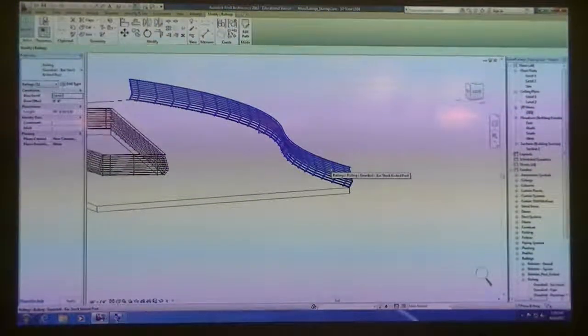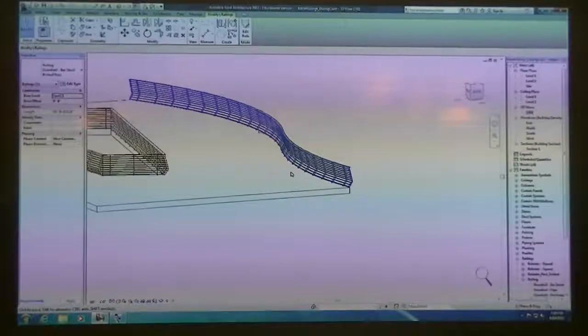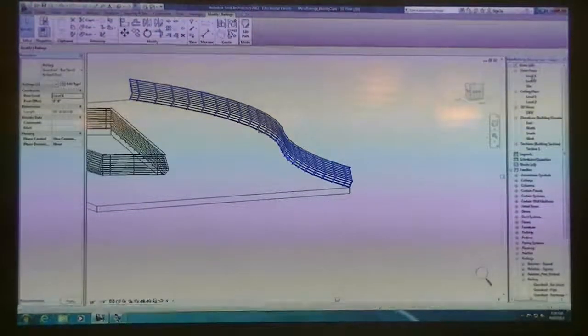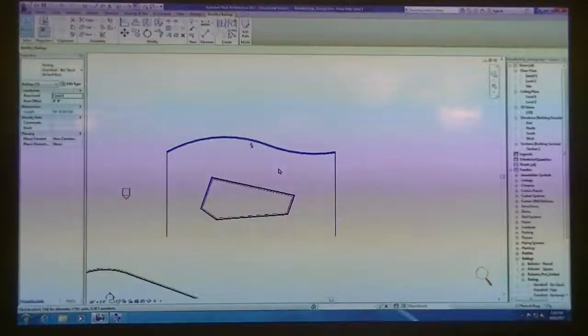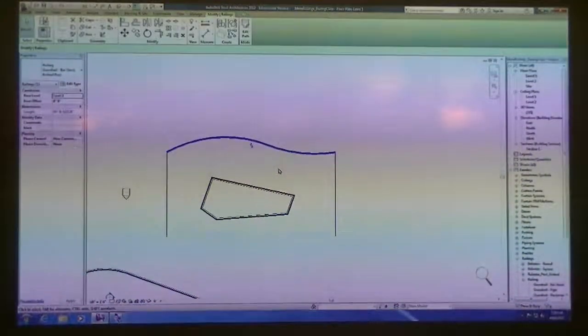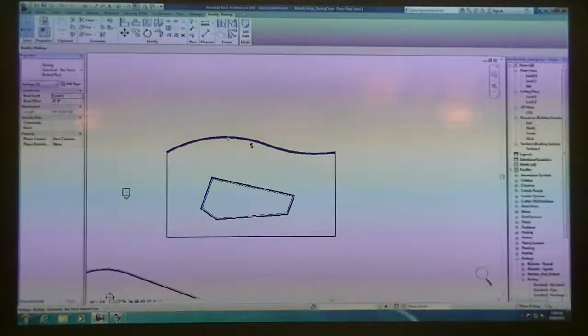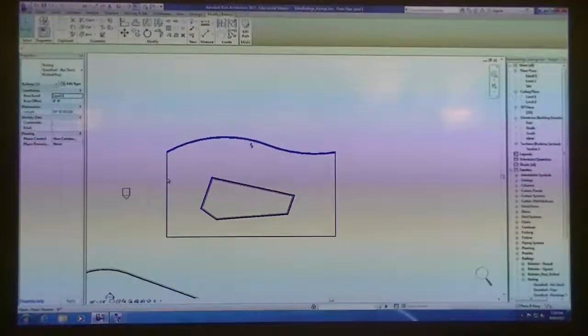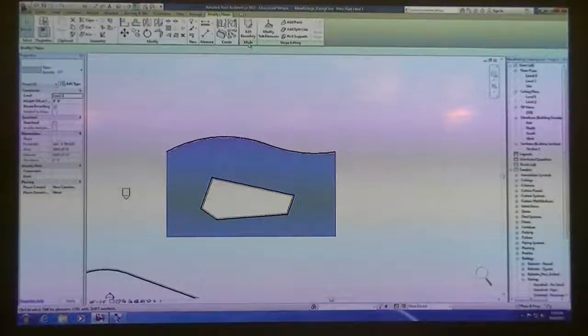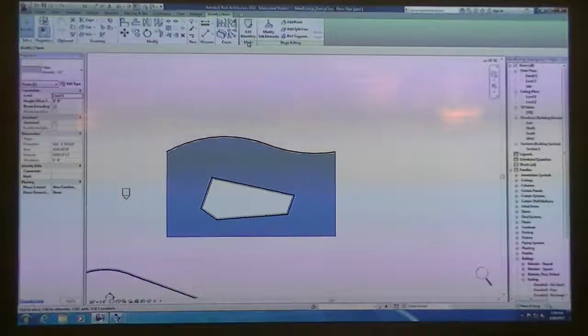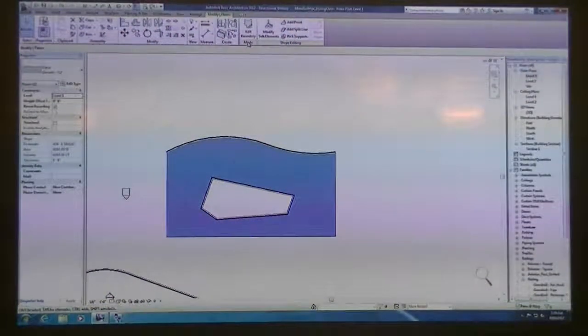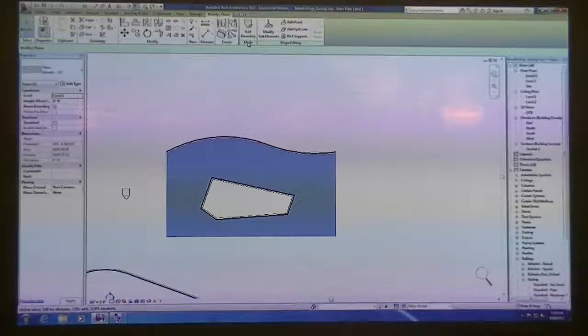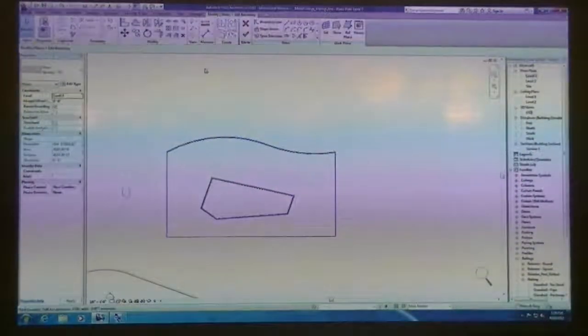On your floor plate, because our floor plates were generated by a mass that might have a curved face to it, some kind of curving happening, you may have to click on your floor plate. And as long as you're not going to edit your mass anymore, you're satisfied with the actual design of your exterior volumetric shaping, you can click on edit boundary of your floor.